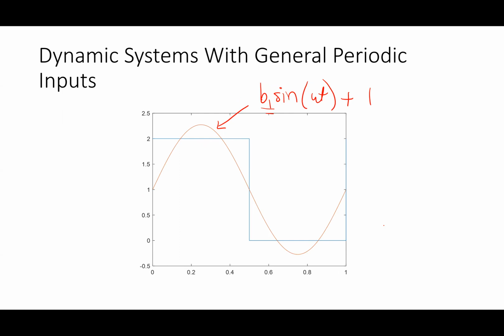Now that's not good enough. So what I want to do is keep adding more sine waves. What's true about the sine waves that I add to it? What did I say last time? How are they related to each other? They're harmonic. What's that mean? We're going to talk more about that if you don't remember. What does it mean to say that they're harmonics? They had to be multiples of each other, integer multiples specifically. And it turns out for this particular waveform, it has to be odd integers.